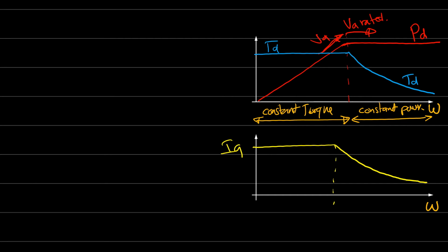Okay, how can we control with the field current? As we said, we can change either the voltage via armature voltage, or the field, or the armature current, right? So we have some arrangements that we can use in order to make either motoring, like increasing the speed, or braking. We have several types of braking, how to stop the motor from moving. And then you'll find that we have either the regenerative braking, dynamic braking, or what we call plugging. Okay, so let's move now and see the mode of operations for this kind of motor.